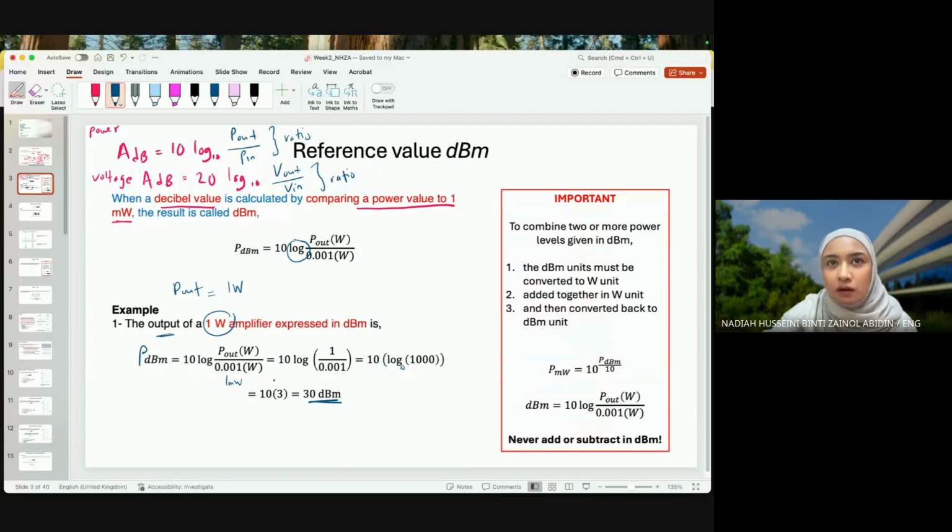Now, what is the function of converting this into dBm? It's actually for optical engineers to design a system. When they have something in dB and dBm, it's a lot easier to calculate the gain and the attenuation and what you need to get rid of. It's just easier. So this is like the starting point to become a designer for optical systems. You can't really see the beauty yet, but you need to bear with it. This is how you build up your fundamentals, so it is very important.